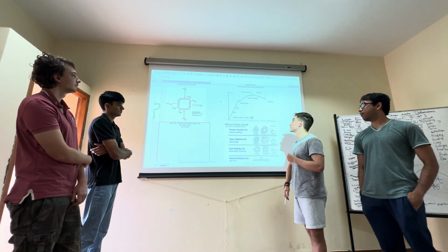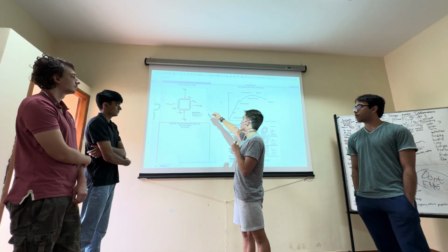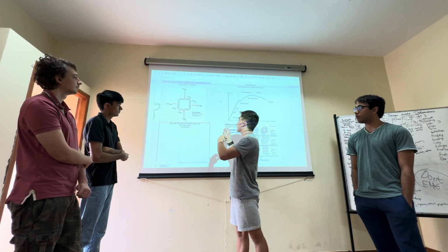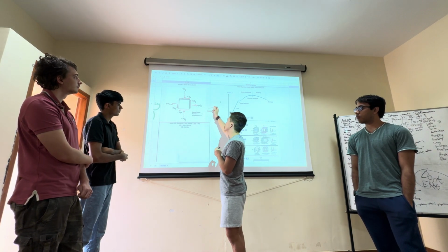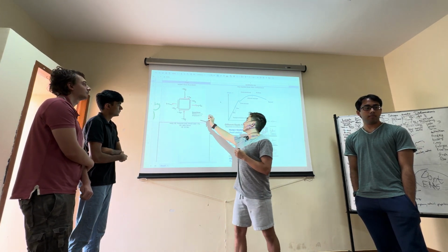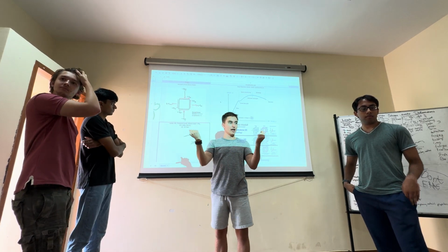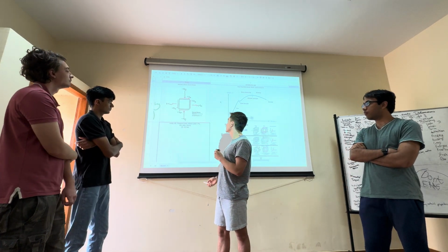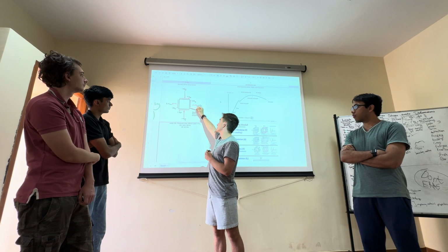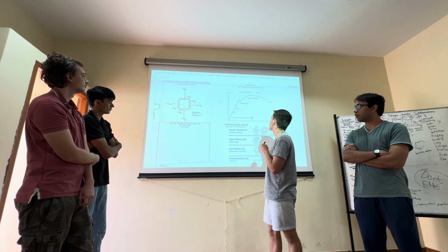And then, of course, there are also the stresses on an object. So we have the normal and shear stress model, and you can see where we have both shear and tension and compression. We always define stresses based on their direction: if a stress is coming this direction, we consider that tension, just pulling out, versus compression, where it is pointing in. Then we have the diagram of all the shear stresses that come alongside the edges of the cube we just used as an example.